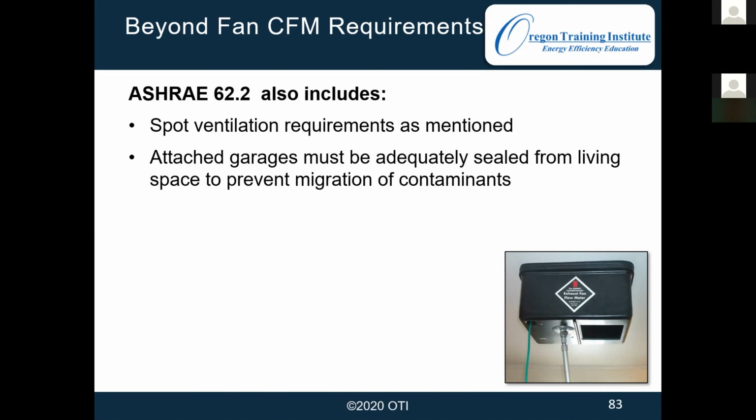But ASHRAE also requires that any penetrations between the garage be sealed, and that's regardless of whether it's cost effective or not.